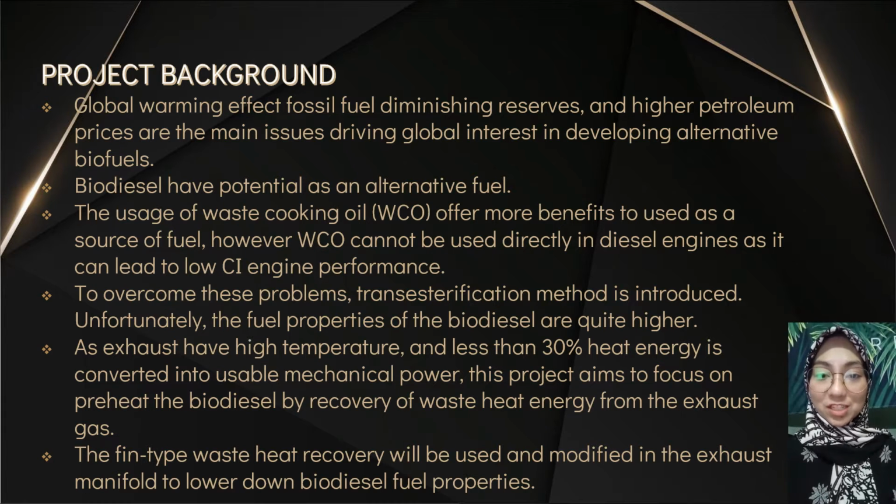But virgin vegetable oils are pricey and also preferable to use as food. Thus, the usage of waste cooking oil could offer more benefits. However, waste cooking oil cannot be used directly in a diesel engine because the fuel properties can lead to engine deposits, piston sticking, and injector choking. To overcome these problems, the most popular and commercially used technology for biodiesel production is the transesterification method, used to optimize these undesirable results.